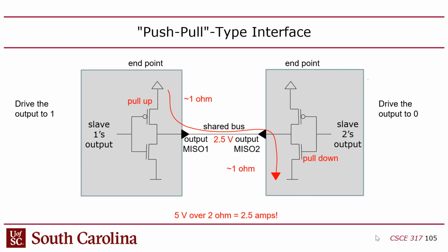Now, if it's an Arduino that's powered by USB, USB is limited to 500 milliamps, right? So it'll peak out at whatever your power supply is. If you can't source 2.5 amps, then you're not going to get 2.5 amps. But whatever the case may be, if you turn them both on, you're going to saturate your current. If you can't supply 2.5 amps, then it's going to cause the voltage across this thing to drop.